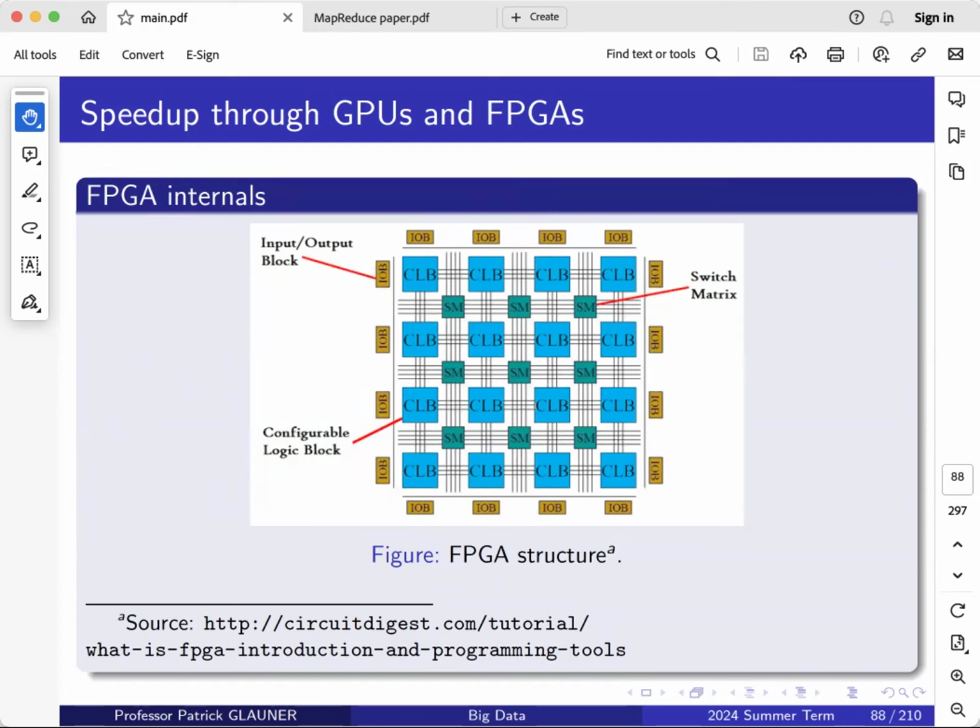In an exploratory data analysis, you would just generate a histogram of your data, and for this data set you would get something like this. We see this is in millimeters. It starts at around 1.6 millimeters up to, I don't know, 4.8, 4.9 millimeters. And we see there is a peak around 2.7 or 2.8, which seems to be the mode of the data, that just the relative majority of bottles have a wall thickness of something like this.